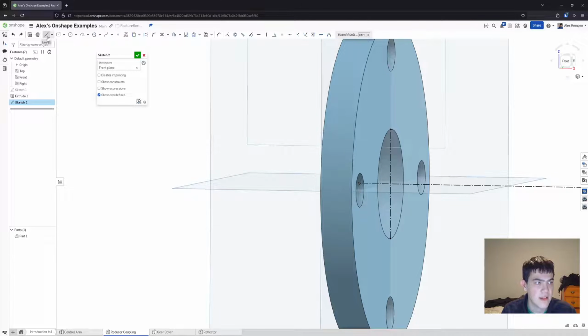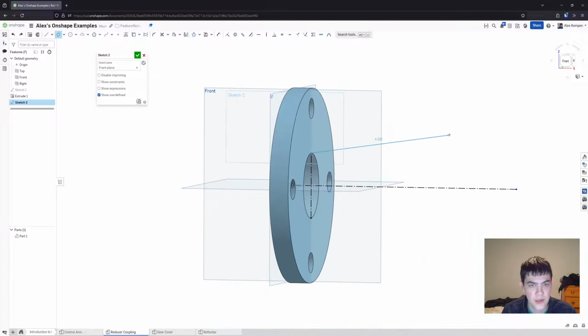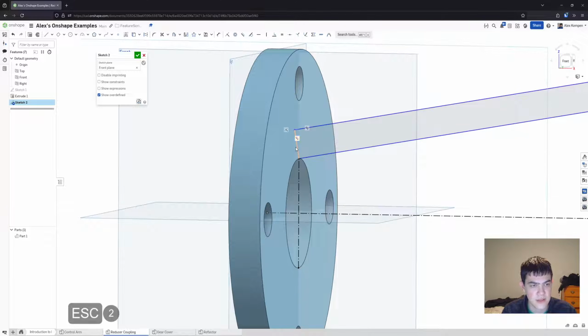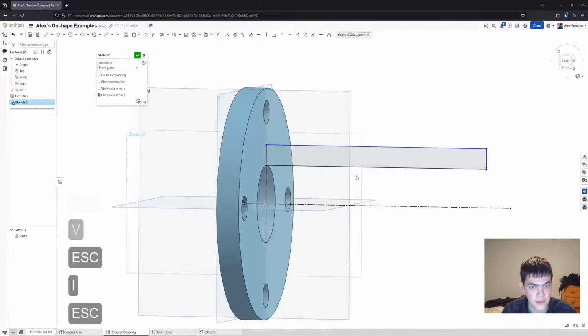And so once we have that line, then we can go ahead and sketch the rest of our stuff. And then one thing you want to be careful of here is this is kind of like a slanted rectangle. So you could use an aligned rectangle here, for example, something like this. But you do have to note that it is slanted, so it's actually more of a parallelogram. So this has to be vertically in line like this, right? So we want this to be in line with this edge, for example.